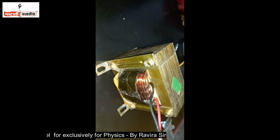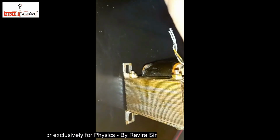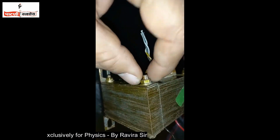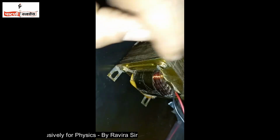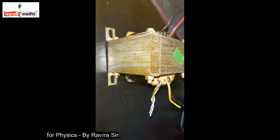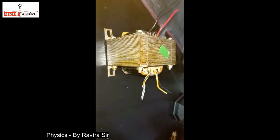And the laminations are arranged such that they are very tight to each other. We can tighten them by using a nut and bolt system. Here the hole is made, and from here one screw is drawn, and we tighten the screw so that all laminations remain very tight to each other, so that an air gap should not be present between the two laminations.